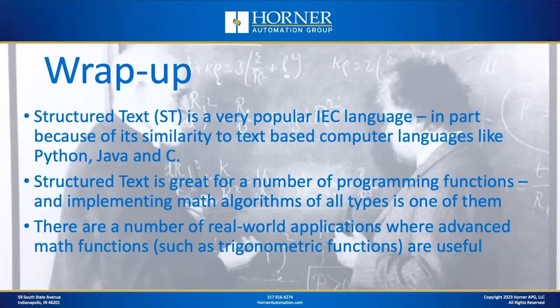Structured text, as we discussed with Casey, is a very popular language, especially since it's similar to text-based computer languages that a lot of folks coming out of college are familiar with. Structured text is great with loops. It's great for searches and finds. It's great for math, and it does that very well. There's a number of real-world applications where advanced math functions can be pretty useful, and of course, we know there's an infinite number of applications where just the basic math functions are useful.